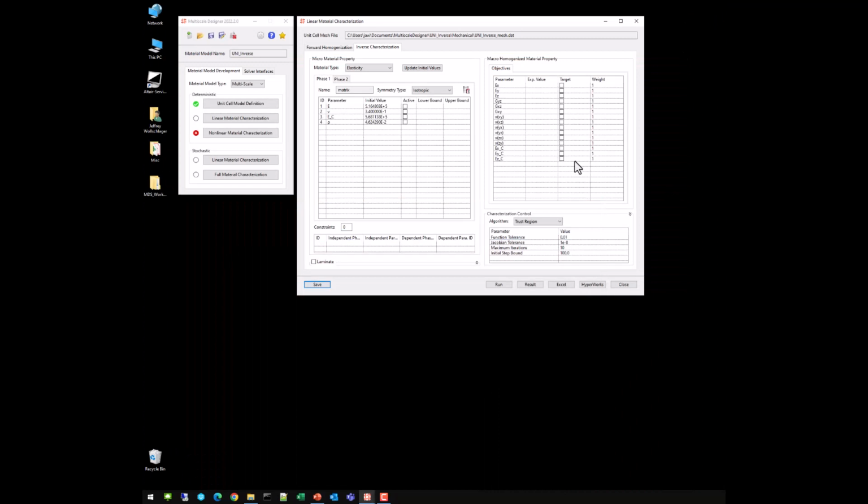So let's do that. We have our initial constitutive matrix and fiber stiffnesses entered already. Let's go ahead and enter in the test data, the experimental data for the homogenized ply itself. So EX is 18.209 e to the 6. EY is 1.219 e to the 6.